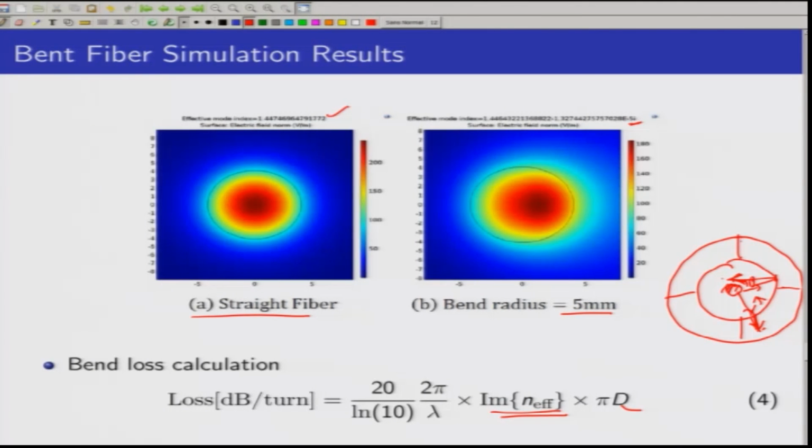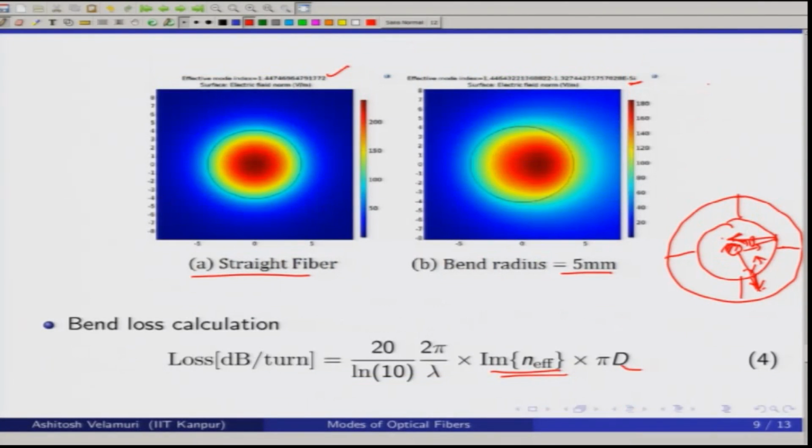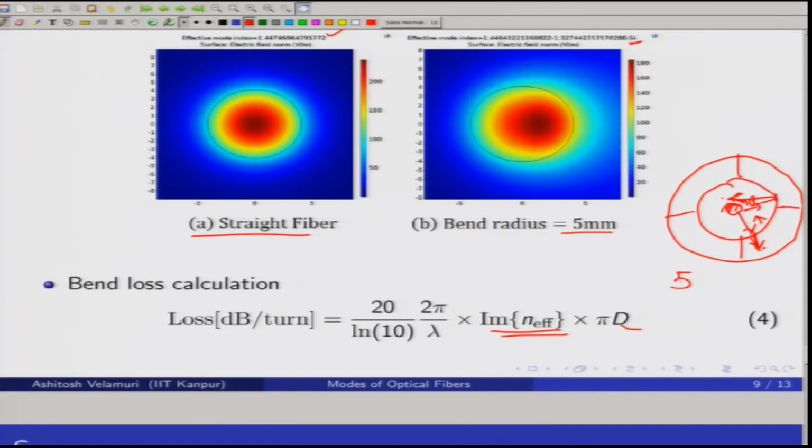So, now the results that we have obtained here, the imaginary part, is after applying the PML layer whose thickness is generally 5 lambda to 7 lambda, where lambda is the operating wavelength.